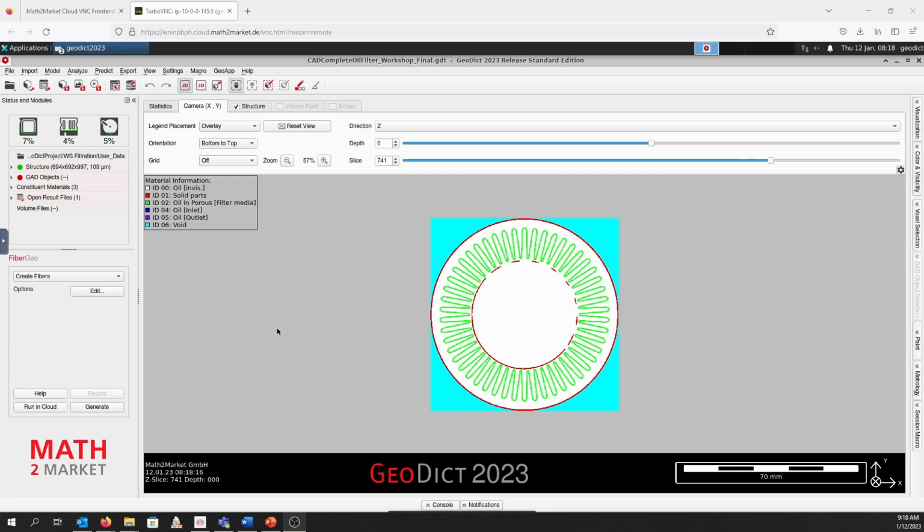So now in the next step, we want the generated pleated structure to be inserted in the original structure. And this should be a one-to-one replacement. So we want to reassign in the first step the existing pleat structure and then insert the new structure with either a different pleat count, which is in our case holes, but we could also have a different thickness or a different amount of porous layers which you could insert here and then have a new structure here.